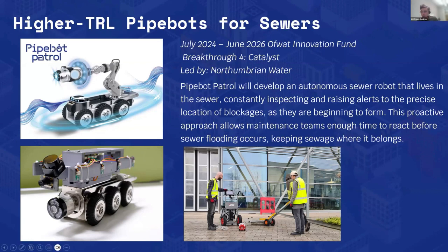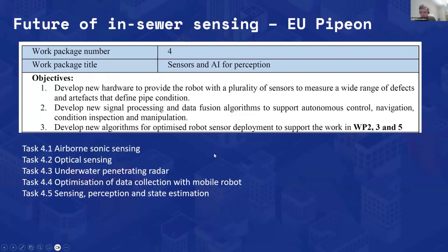What we're working on now is that acoustics on its own is not good enough, because ideally we'd like to map the pipe in greater detail. So we begin to deploy a plurality of sensors, like the traditional video camera, but also LiDAR, which produces a really high quality map of the pipe. And that takes us to the penultimate slide, which is to do with the future of in-pipe sensing, and that's the combination of several sensors, or sensor fusion.